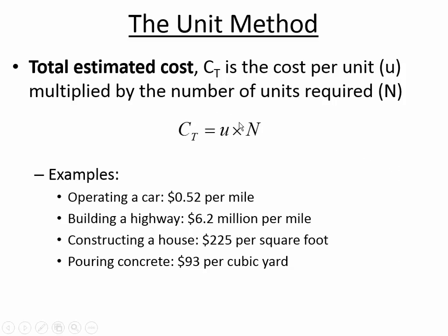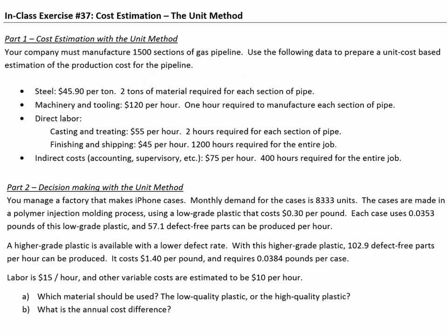The idea here is you have the unit cost, and then you decide the cost of the project by just multiplying how big the project is going to be by this unit cost. So if your apartment will be 100 square meters, and you know the cost per square meter, that gives you a rough idea, a very quick estimate of how much it may cost to construct.